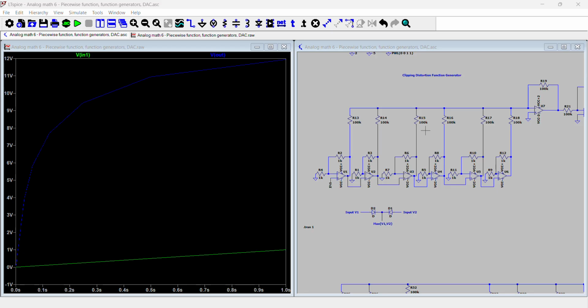First, I discovered the circuit through analyzing log amps, because this is a known piecewise function to approximate logs. And you can see why. It's because the rate of change is proportional to the current voltage. The higher the output voltage, the more stages are in cutoff or saturation, so the more stages don't contribute to the slope anymore. And that's just the inverse of the exponential relationship, where the rate of change is proportional to the current output value.